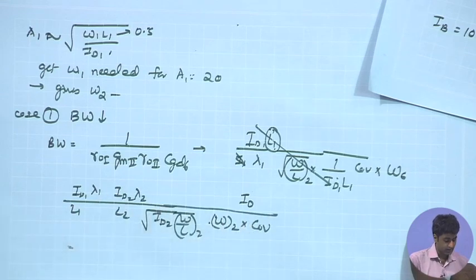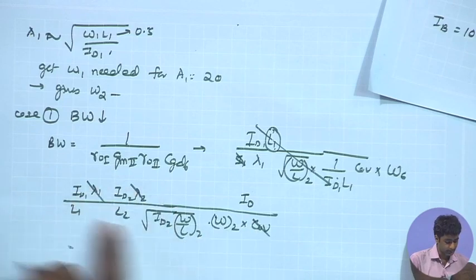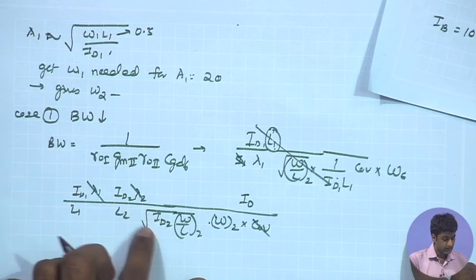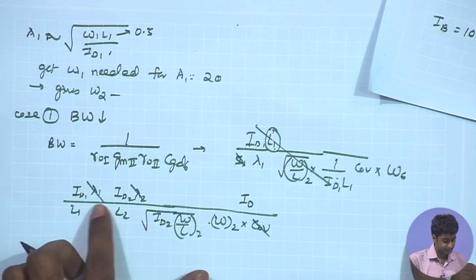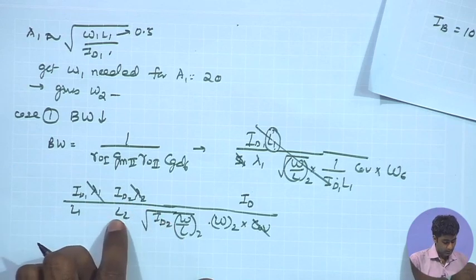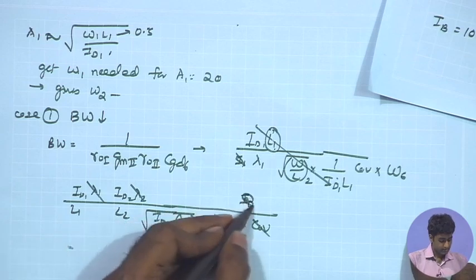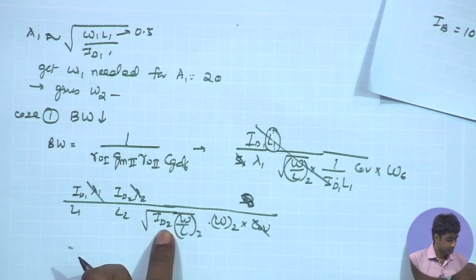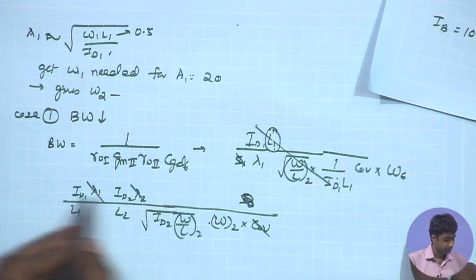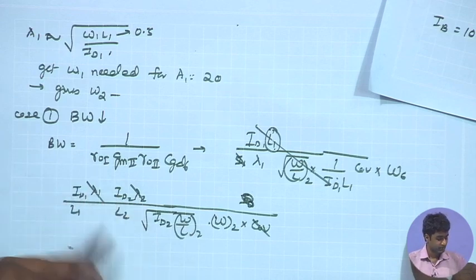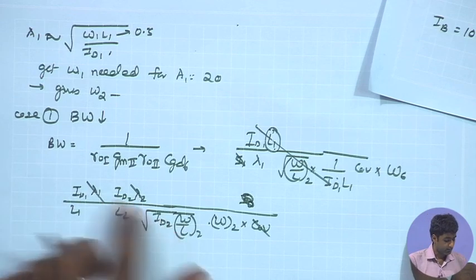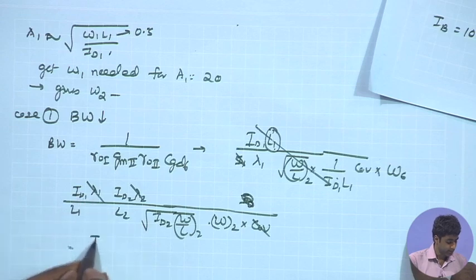This is not in our hand. Likewise, these two are also not in our hand. So, I can get rid of these, and I am left with this particular quantity. And once again, if I assume that the overall bias current is similar in both the cases, these are just going to give me the same values of bias current, and therefore, I have a strong dependence on ID.